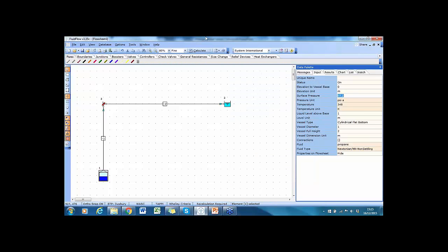And now we just edit the design input information. So it's 300.7 psia and 60 Fahrenheit is the temperature. And again, the default information we can just leave as is. Go back to the relief valve. It's the API standard. It's a sole device, 10%. Set pressure, 260 psi gauge. And the flow rate was 100 gallons per minute. So it's down at the bottom here. It is US gallons per minute. Okay. KD in this case was 0.65.